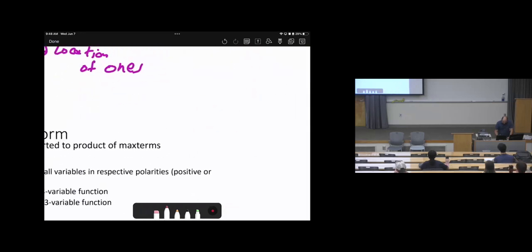So just a quick review. Let's assume M4 as min terms. It is in binary 1, 0, 0, and let's assume the variables A, B, C. It will be A, B bar, C bar.